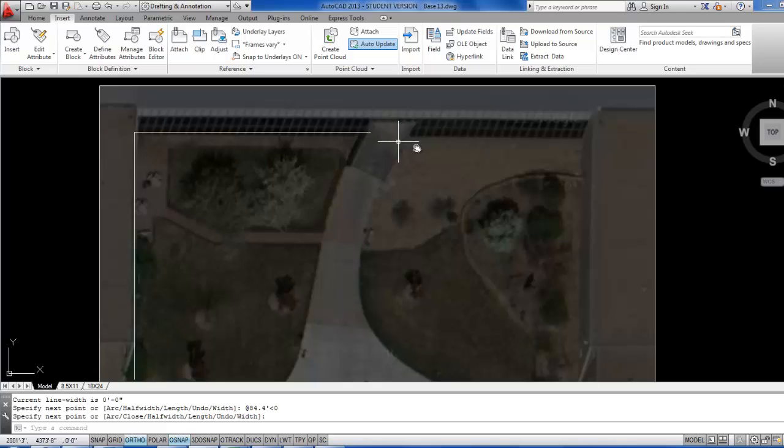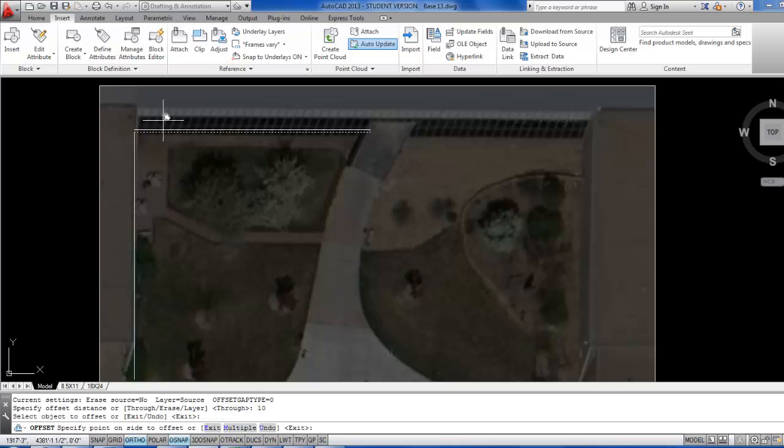I do have a note that I have a 10-inch offset. So I need to offset both of these lines by 10 inches that I missed the first time. There seems to be a foundation or something that sticks out about 10 inches, making this exact point about 10 inches off. So I can use the offset command, 10. I'm going to go in both directions.